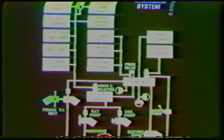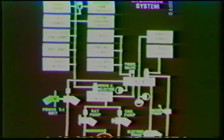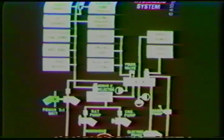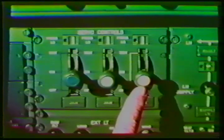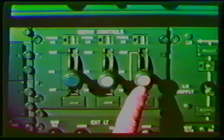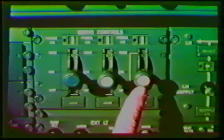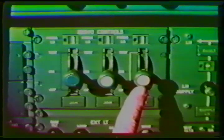If system pressure drops below 1,885 psi, the valve closes, isolating the stabilizer from the servo control manifold. The yellow servo control lever and the related servo control manifold function as described for the other systems.